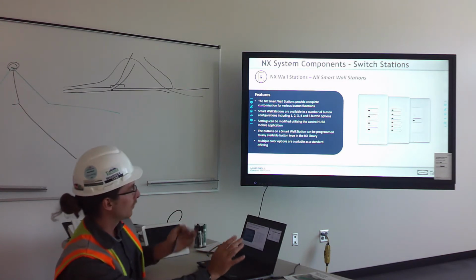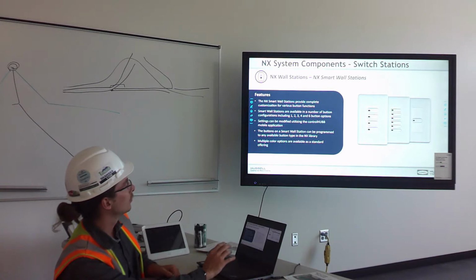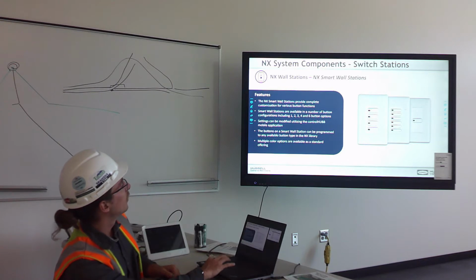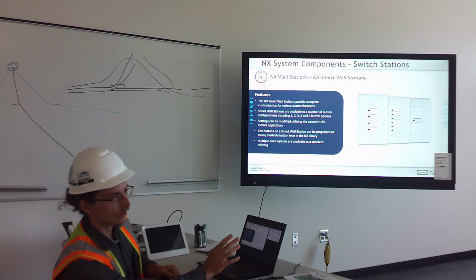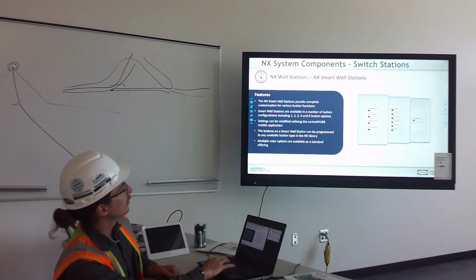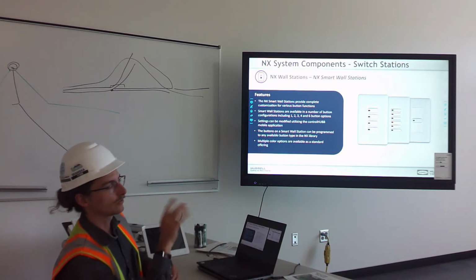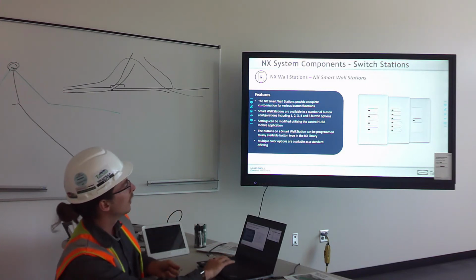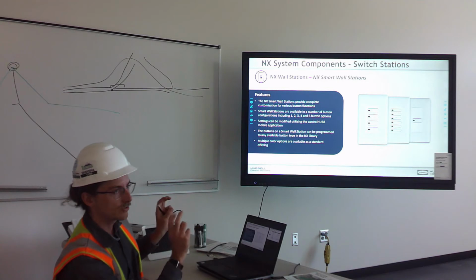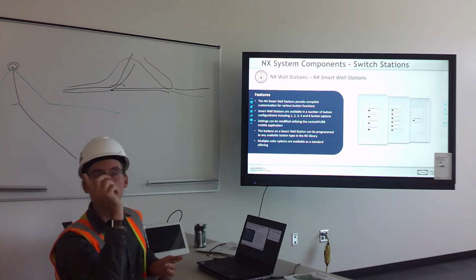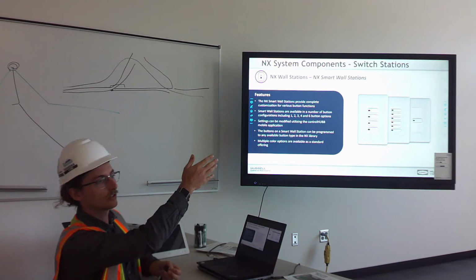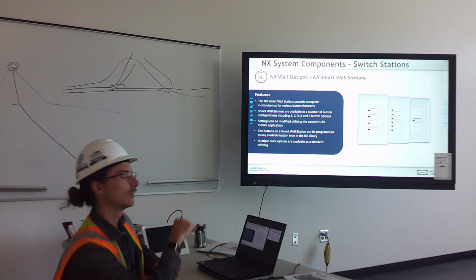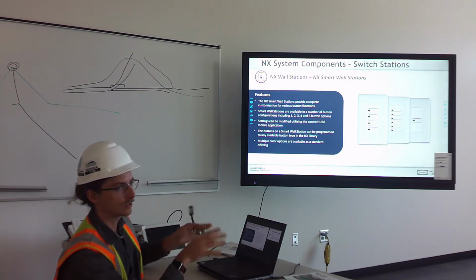And so those have been programmed to how the sequence of operation calls them out, which I'll run through right now. For the 6 buttons in all the classrooms, the top button is on and off for all the lights in the room, just standard toggle. The second button activates your AV preset, which is what we've got going on right now in here: the row of lights in the front of the room totally off, and then the back row down to 25%. So you hit that button, it'll just activate that preset, and that's that.